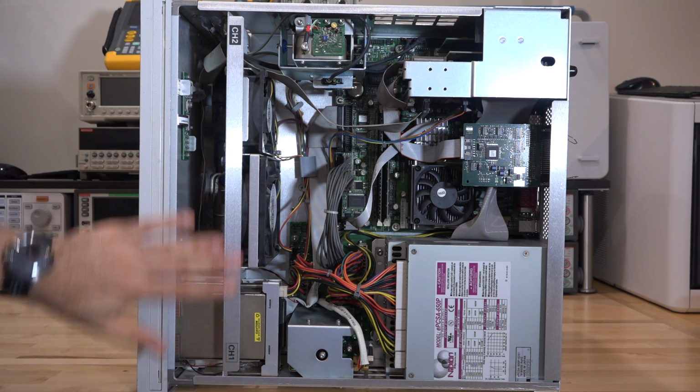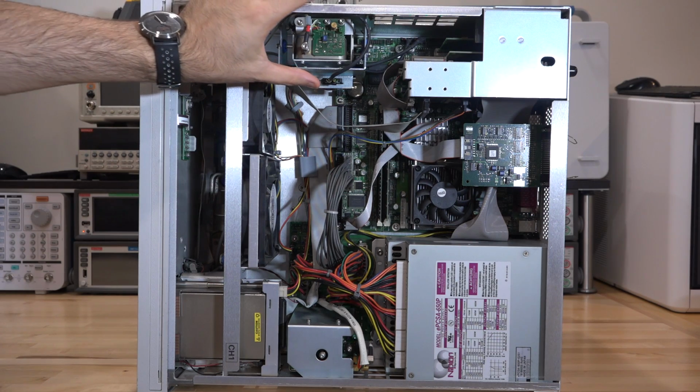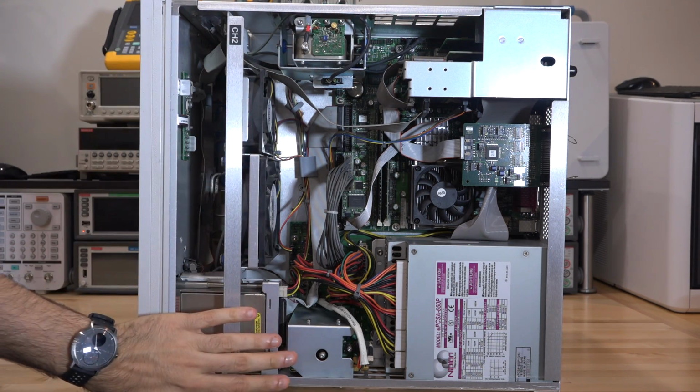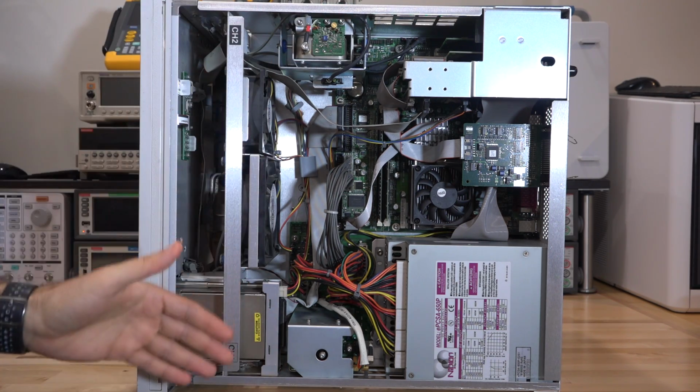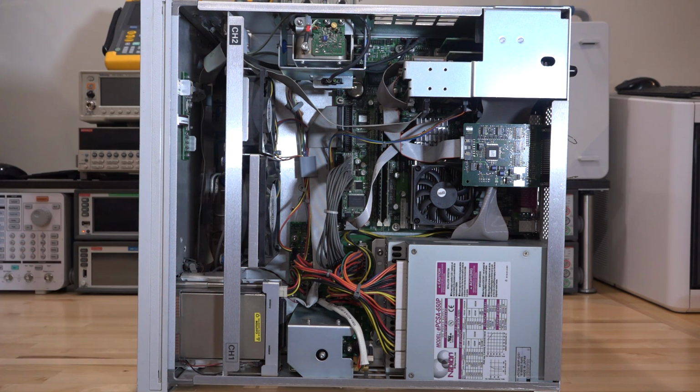Now if you look, here's the channel 1 and channel 2 portions. This is the oven controlled crystal oscillator for one channel, this is for the other channel. Interestingly enough, they are from different vendors, it looks like, and that might be partially because they want to decorrelate the core PLLs of the two LO signals inside as much as possible. As I spoke about, that decorrelation is really important, it allows you to eliminate the phase noise of the down converters from the entire phase noise measurement. That's the whole point here. Maybe that's the reason why they've done this.